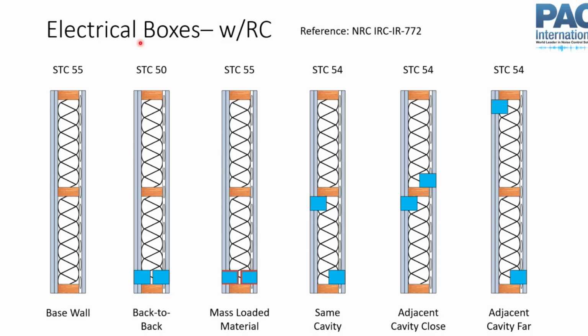So one way that you can try to address this is you separate these things further from each other so that the sound has to travel further through them, right? You're not really addressing the structural path per se, or really the cavity path. You haven't actually changed anything. You just make the sound have to travel further through that cavity path to get from one weak point to the other. And that can improve your SDC rating and get it back to basically where we started.